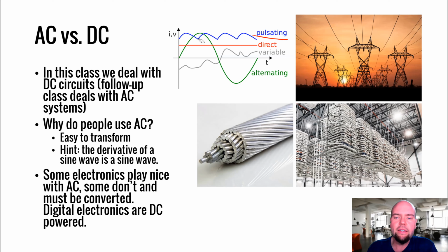And the reason for that is power losses are I squared R. So if we have a resistive wire, we generally want to keep those currents low to avoid those I squared R power losses. The only other way to avoid it is basically to have a low resistance in the wire, which means paying for this really gigantic conductor if we wanted to keep the resistance low.